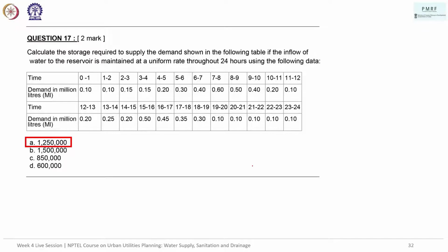In this case we are not taking into account the fire demand and the breakdown demand. If you calculate that as well, then the value will be slightly higher. Breakdown demand is usually 25% of what is required per day, or 1 to 2 hours of uninterrupted supply, if I'm not wrong. And fire storage will be 5 liters per capita.